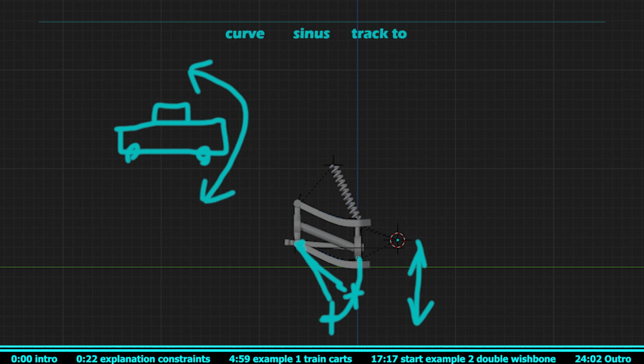But the issue with this is if you rotate the body where it's parented to, and you did set up the parents right, then this empty is trying to go up and down while it's rotating. If you have a circle here and you have an empty here and you rotate everything, this also goes up on the z-axis.